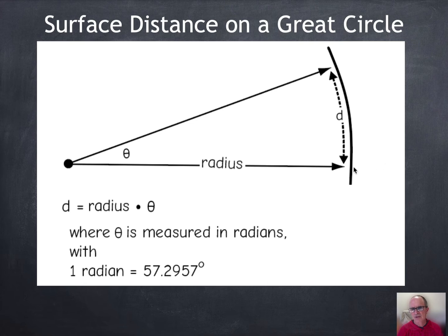So we can make a measurement to a star from 2 locations, and that difference in the angle we can measure. And from that difference in the angle, because we'll measure basically a local vertical here and a local vertical here, we can measure the angle of the stars, and through some trigonometry we can figure out what this angle is. And if we know what the radius is, we can get the distance. So we often use these radius measures along with angle measures to get distances in spherical surveying.